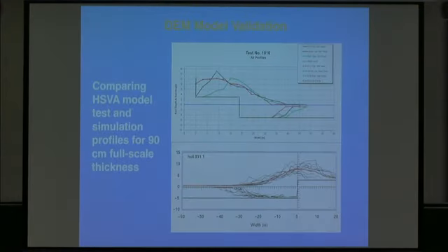Okay, so back to those tests at HSVA, the physical model tests. These are profiles of the physical test here. The maximum sail height's around 12 meters. This is a 3 meter freeboard, 5 meter depth. This is the grounded portion in front of the structure. Unfortunately, this is flipped around backwards, but it's the same idea. This is the superimposed profiles of 10 simulations.